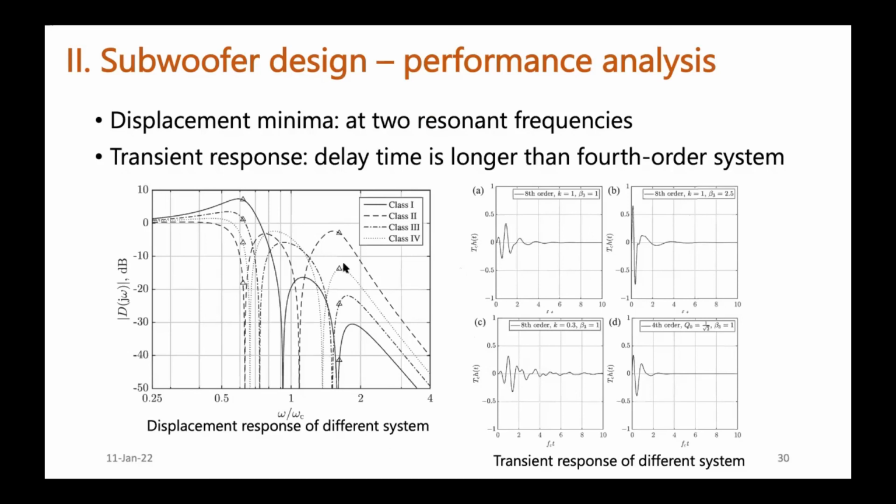And we can also find out the displacement response and the transient response of the bandpass subwoofer. And in the displacement response, the subwoofer has two minima, and near the minima, the displacement of the driver is very small, and the nonlinear distortion can be suppressed.